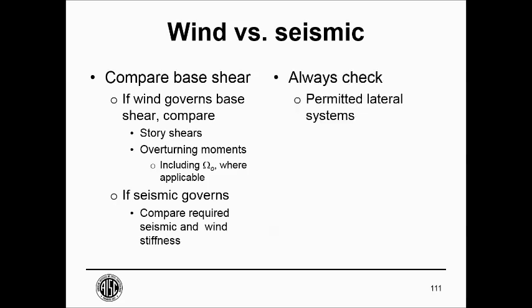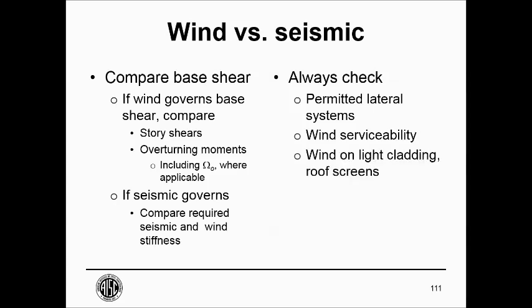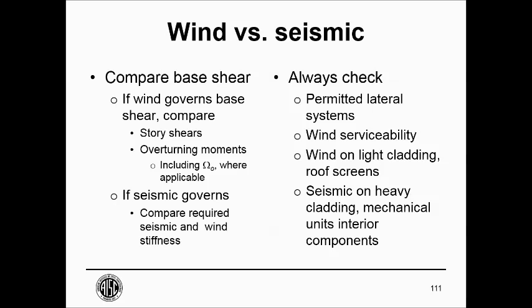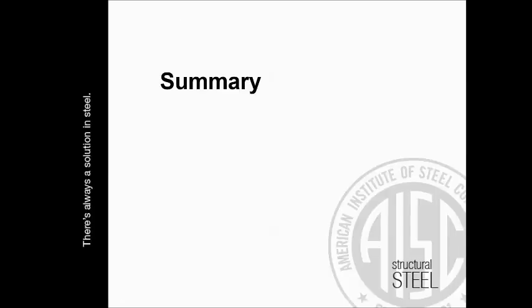You should always check to make sure that the system you're using is allowed in the seismic design category. You should always check the wind serviceability. Always check wind on lightly loaded cladding and roof screens and so on. And always check seismic on the heavier elements and seismic stability.